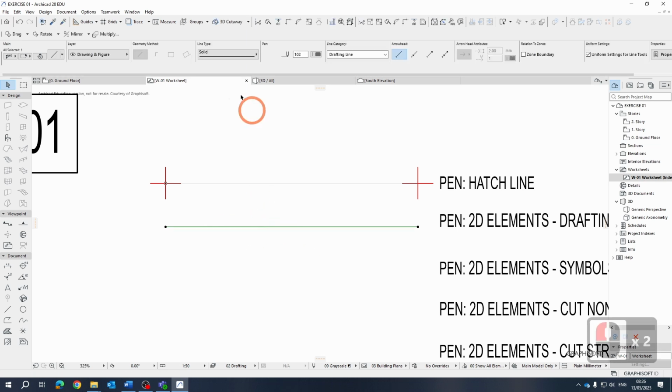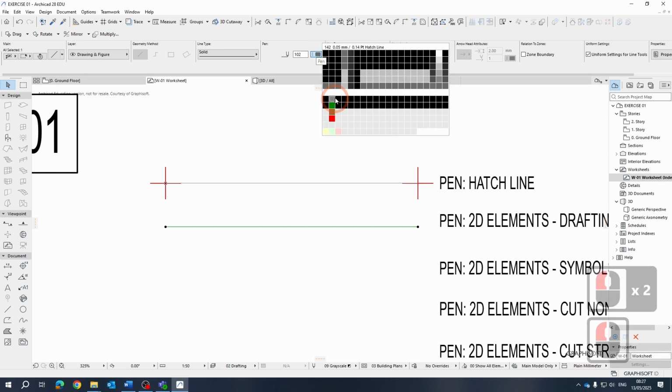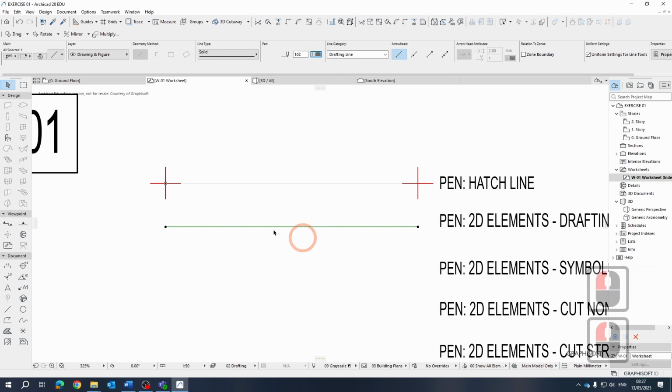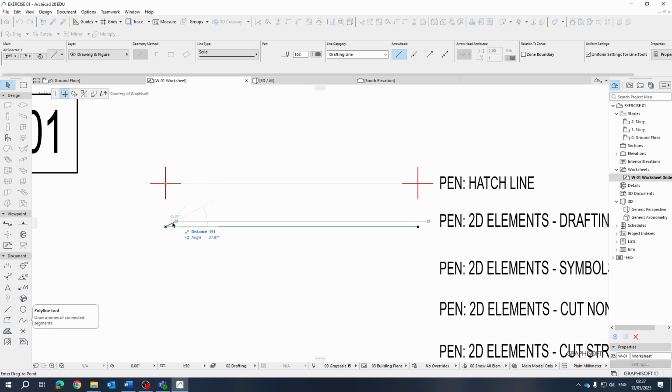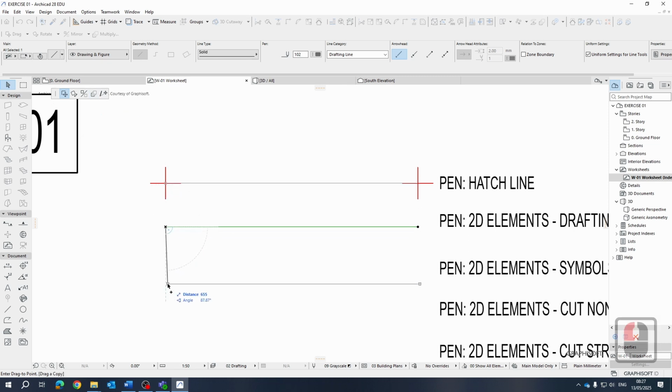Okay. So I've now selected the next element. I'm going to copy this down again. So select this endpoint, and whatever tool you used last with the type of line work or polyline, it will try and use that tool again. So just remember, you need to select, so rotate, move. Okay. So we're going to move this down. So press Control. We're going to move it down again by 500. Just remember, if you lock Shift, it'll lock it on an axis as well, or at an angle. So once you've got that angle, it'll keep it at an angle. So that's quite handy to know. So I'm going to type in 500 again.